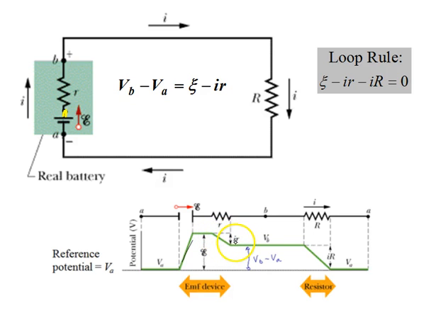That potential decrease amount is I times R. The R we'll consider a constant. The I will vary depending upon our load resistor over here. And again, across this part of the circuit, that's an equal potential. We have no change in voltage. As we go through the load resistance, we again decrease till we get back to our reference potential VA, because this again is an equal potential.